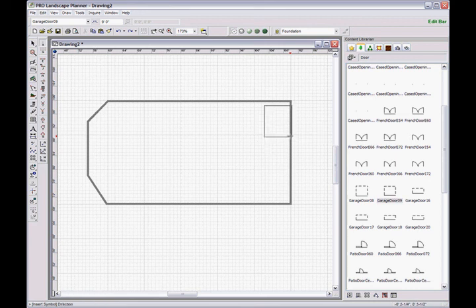And then I wiggle my mouse slightly, and I can either move that left or right. I can move it into 4 positions around that point. So let's go ahead and click here and drop it like so. Now if I want to place another one, I can do that just by coming in and clicking again on the foundation line just below that one. Set it there, and then wiggle it just a little bit to find the location that I want to drop it to, and do another left click to drop it down. I'll go ahead and do a right click to deselect that.